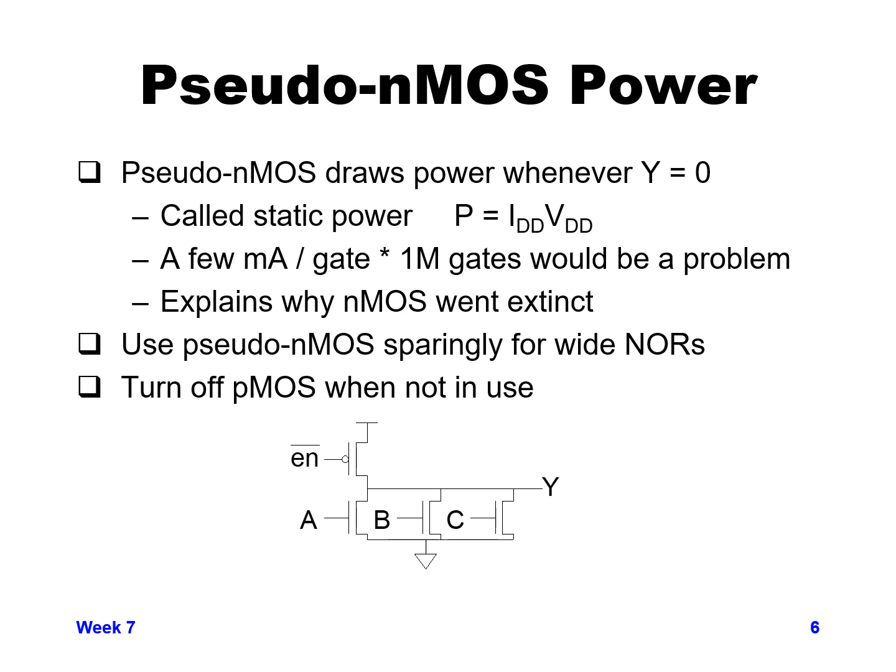It's power that's always happening, a constant current flowing whenever you're trying to get a value of 0 out of these gates. And so this power is a static power. That's the current going through the PMOS and NMOS device, the same current through both of them, times the voltage difference of your VDD rail.